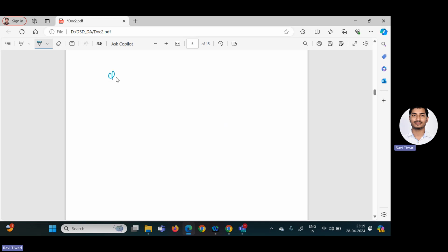So this is Q2, this is Q1, this is Q1 plus 1, and I'm writing the excitation table of D flip-flop. So this is 0, 0, 1, 1, 0, 1, 0, 1. So this will be 0, 1, 0, 1.